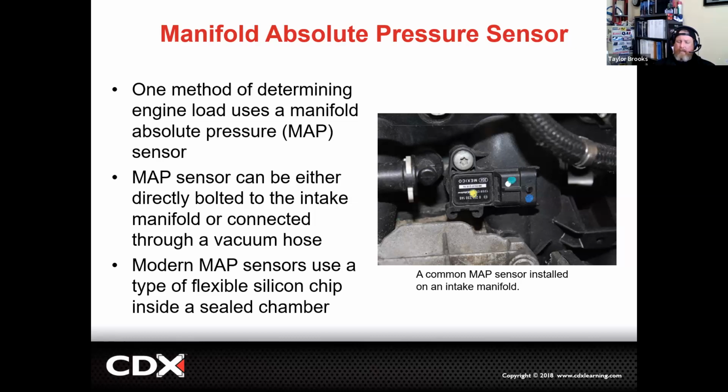That, along with our throttle position, can be used to calculate what the exact load is for that engine. Therefore, if there is a situation where one of the wheels begins to slip, like we were talking about in our electronic limited slip differential lecture, the PCM has the ability to regulate that back and to cut throttle as one of the options it has. Now, if we don't have a MAP sensor, it is a MAF sensor or mass airflow sensor. Those tend to not be used for calculating load to deregulate power at that point.